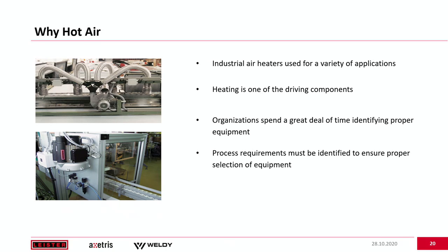Now, some of those applications use a separate heater and a separate blower to achieve those needs. But what if you don't have the required footprint for your manufacturing line, or you don't have the budget to acquire those tools, or you're just exploring some initial concepts? Well, that's where a hot air blower would actually suit your needs.